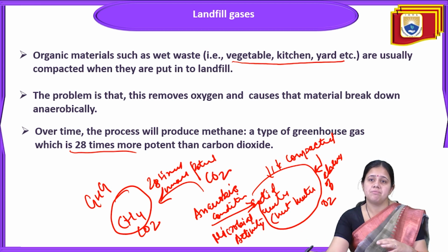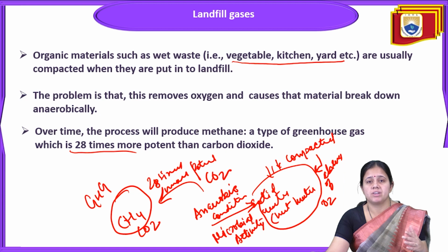In the landfill, we put wet waste like vegetable waste and yard trimmings in a compacted way. Due to the compaction, an absence of oxygen condition is created inside the cell, inside the waste. With no oxygen, degradation starts. Anaerobic digestion takes place, and the microbial activity breaks down the organic material in the waste. By all this activity, two gases originate, called methane and carbon dioxide.